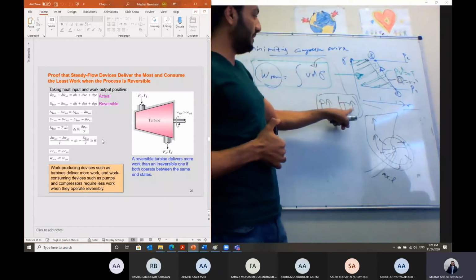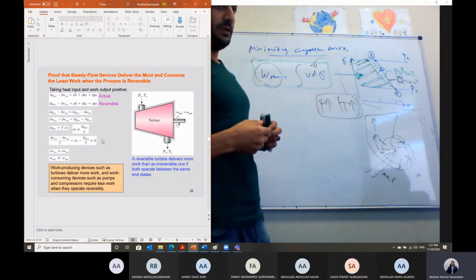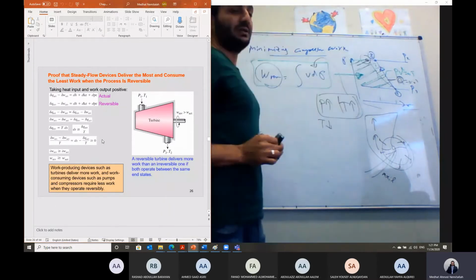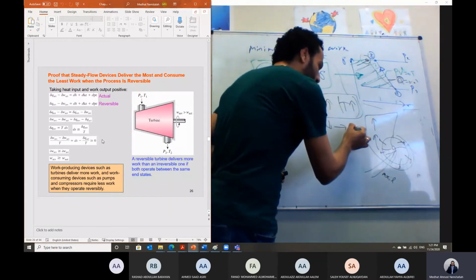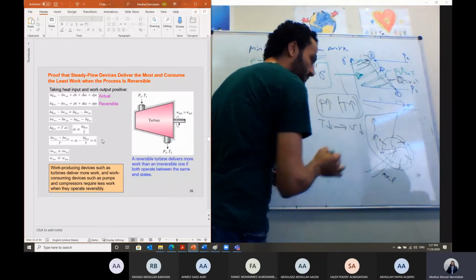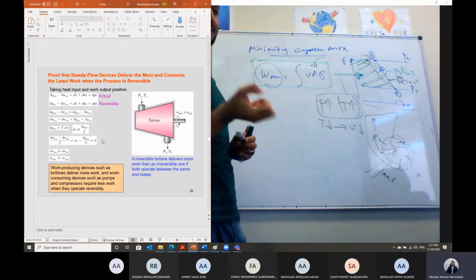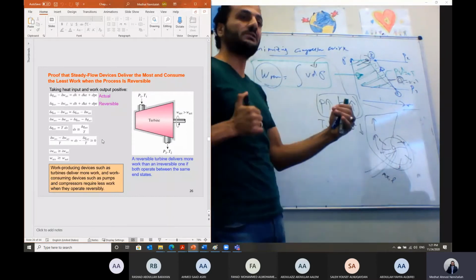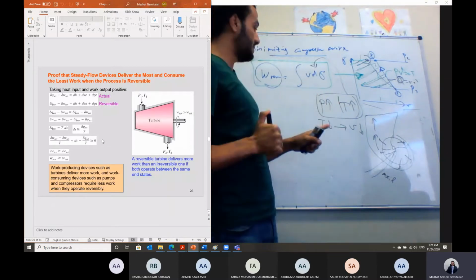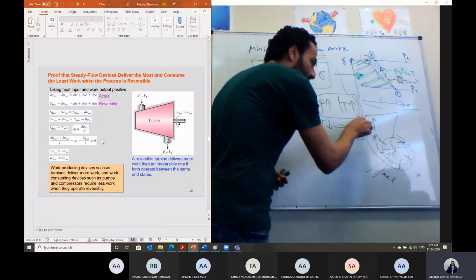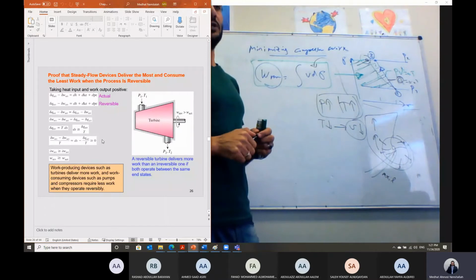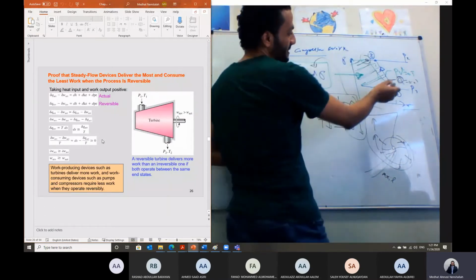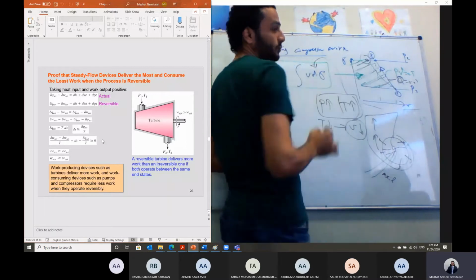That means if I am able to reduce the final temperature a little bit at the exit section, the volume of the gas will be contracted a little bit. So if I am able to cool down the gases during the compression process, I can reduce the final volume. If I reduce the final volume, the area under the curve will be reduced.